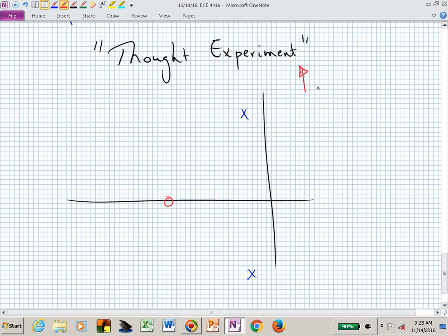Here's the thought experiment: adding only a 0. The reason it's a thought experiment is because we can't just add a 0. That's a pure derivative, and we don't want to have a pure derivative. But this gives us an idea, or helps us start thinking about what putting poles and zeros into the S-plane might help us do. So we're looking to help our insight.